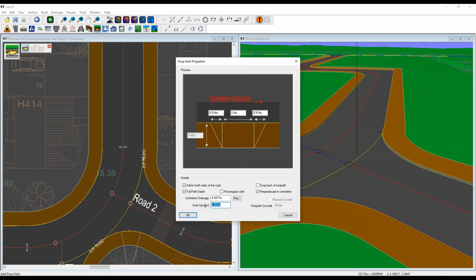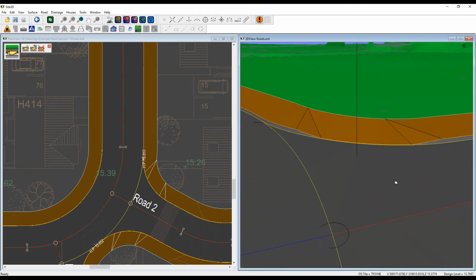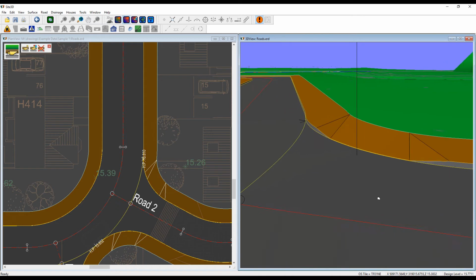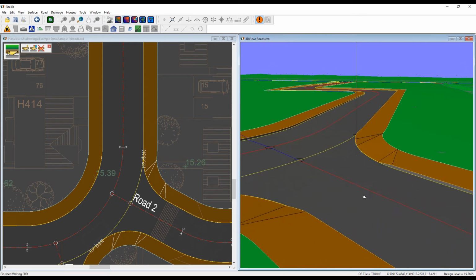The next important thing to look at is the upstand. So for a pedestrian crossing it's probably about 3 mm, you need to make it easy for pushchairs to be pushed up and down the curbs. So click OK, and you can then see we have our 3D pram crossing, pedestrian crossing over the channel there.